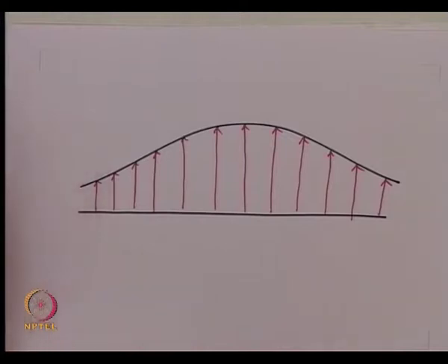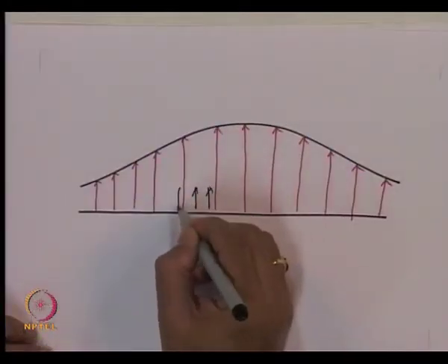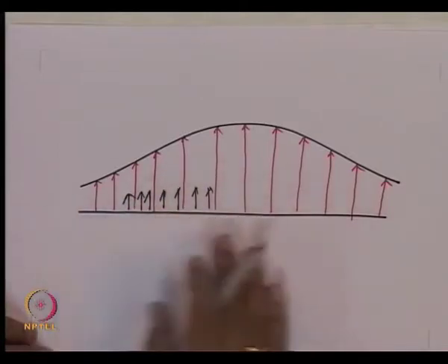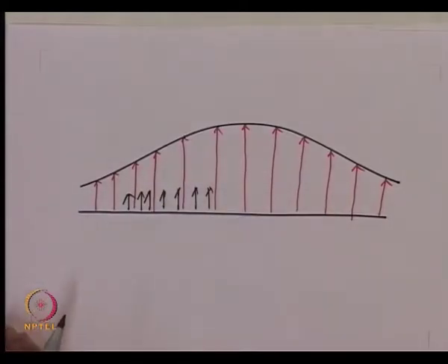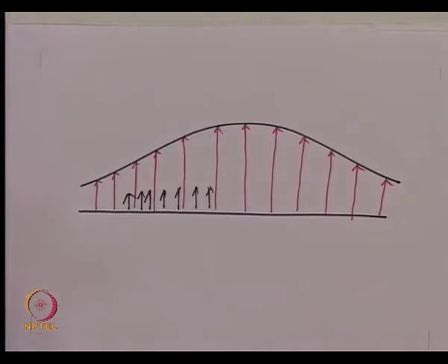So, this system can be visualized as if there is a parallel transmission of multiple carriers taking place. Each one is modulated in an amplitude modulated fashion with the modulating signal. One can say that each of these carriers would have its own sidebands, and that is the reason the sideband information is completely masked, because you have a distribution and sidebands are completely submerged inside this.